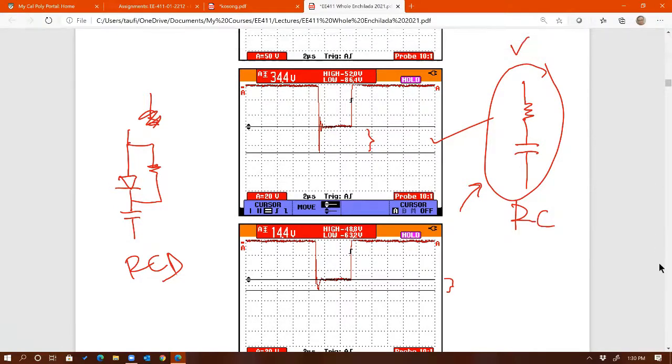Is it more power? More power loss. How come? Because now the resistor is dissipating both ways. Exactly. Very good, Crystal. For RCD, when it's charging, it charges through the diode, so that's practically no loss. The only loss is when you're discharging the cap. When you have RC, you're dissipating power both in the charging path and the discharging path.